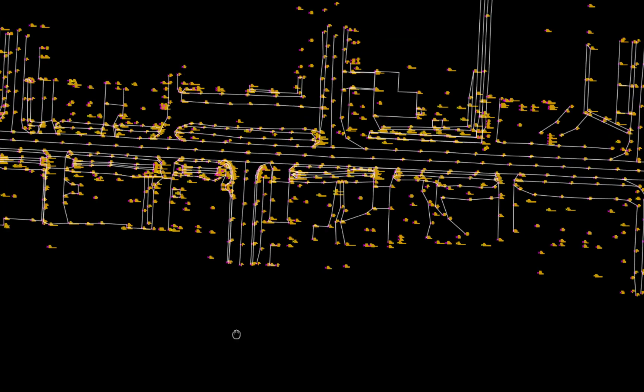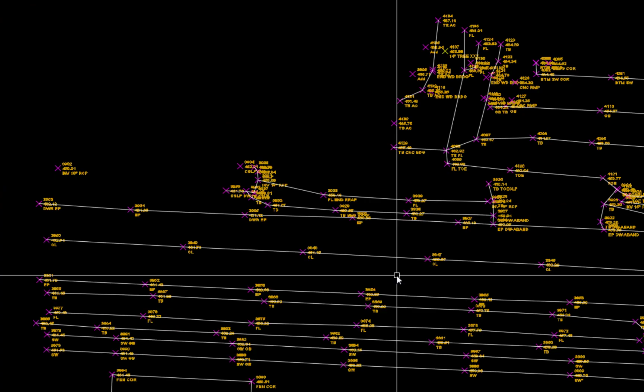For the purpose of this video, the break line drawing for the Kincaid tutorial project has been inserted into this drawing. A closed 2D polyline boundary at elevation 0 is drawn along the outside edge of the topo survey.